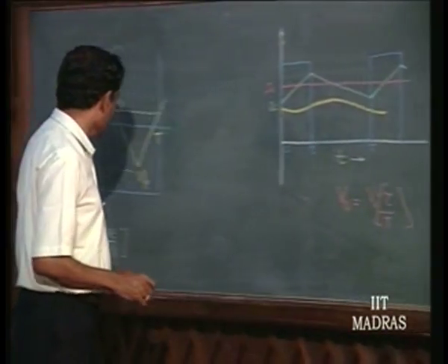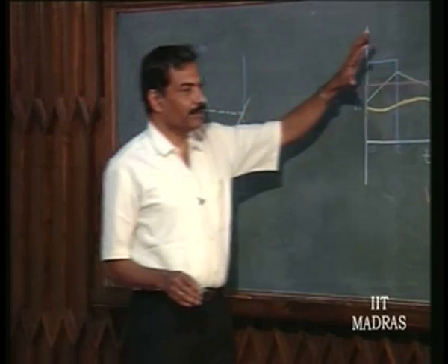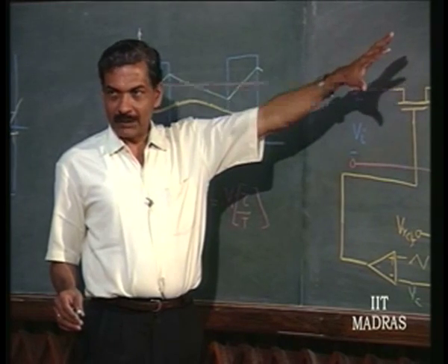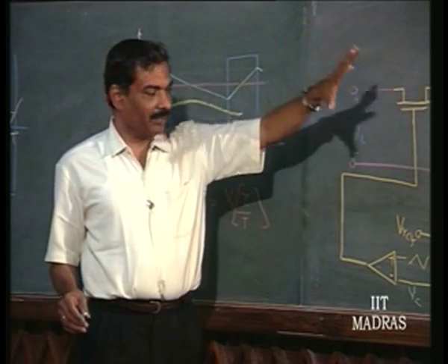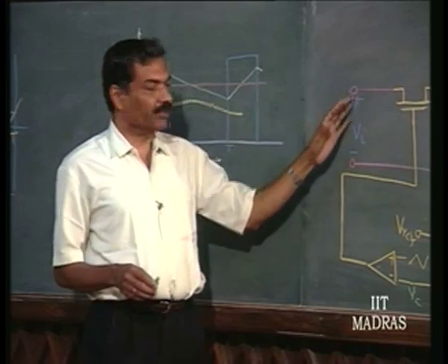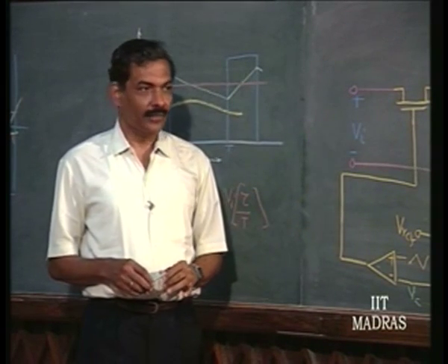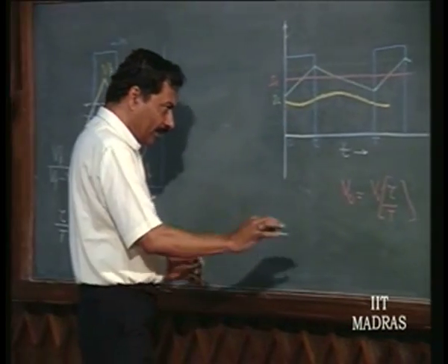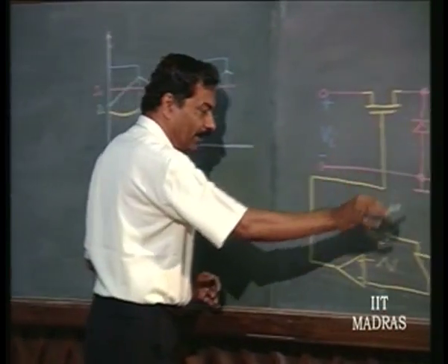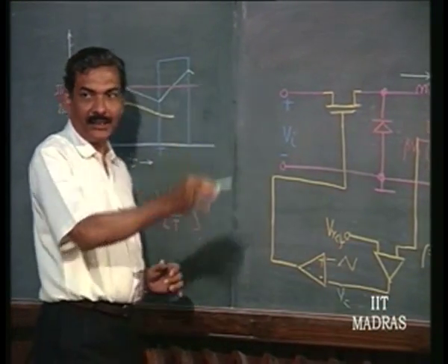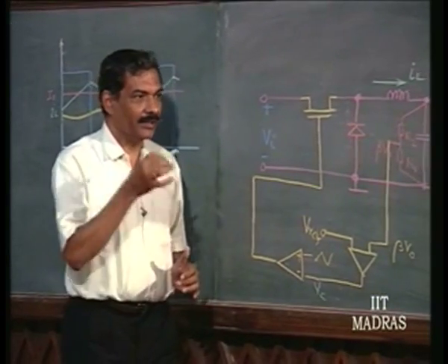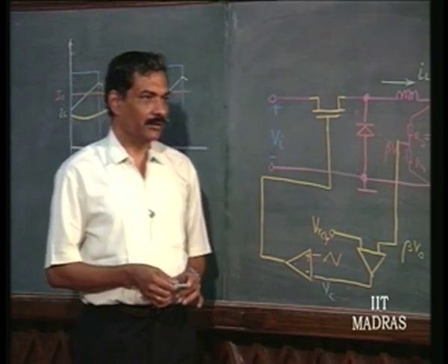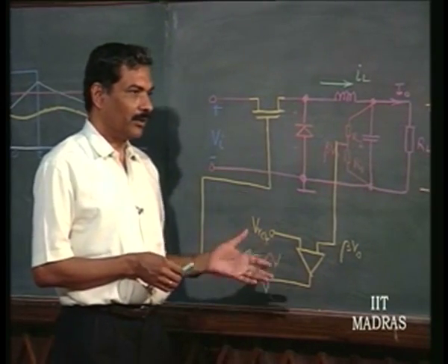So, ultimately, we have been able to obtain a switched mode power supply whose output voltage can be maintained constant irrespective of the variation in Vi. So, I wanted to bring up this idea of pulse width modulation, which is an important idea repeatedly used in IC applications in a variety of purposes, control, communication.